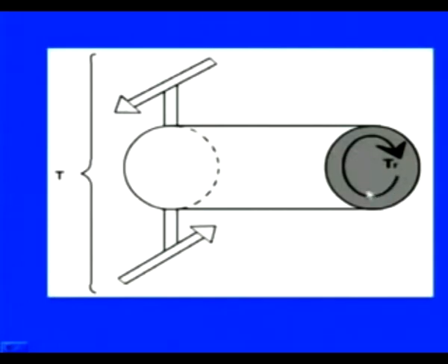The torque is trying to rotate in this clockwise direction, as I told you, and now we have another portion. If we want to make this segment an equilibrium, then we need to apply a torque in an anti-clockwise direction. So this is one significant effect. The middle portion is also affected by the rotation. The layers of the circumference of this particular cylinder will always tend to move in this direction. There is no elongation towards the x direction or y direction; they simply tend to move along the circumference.